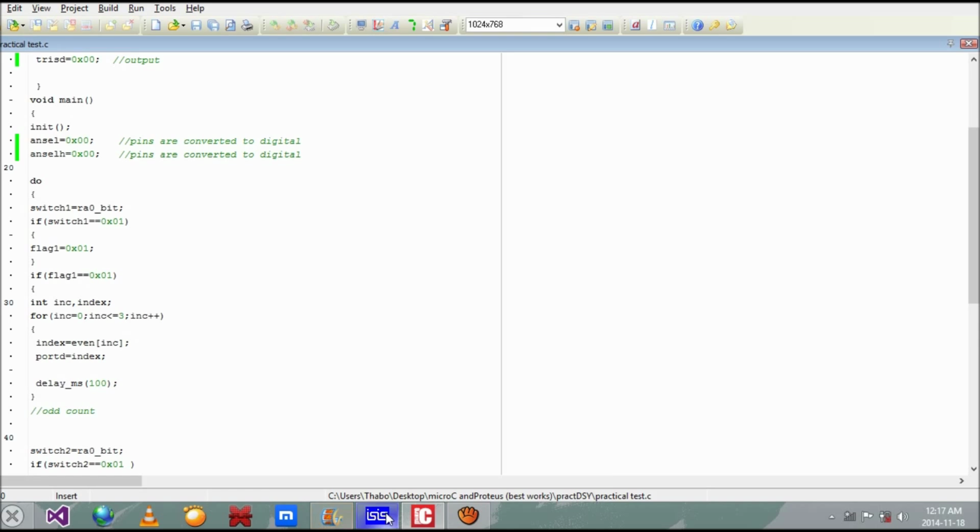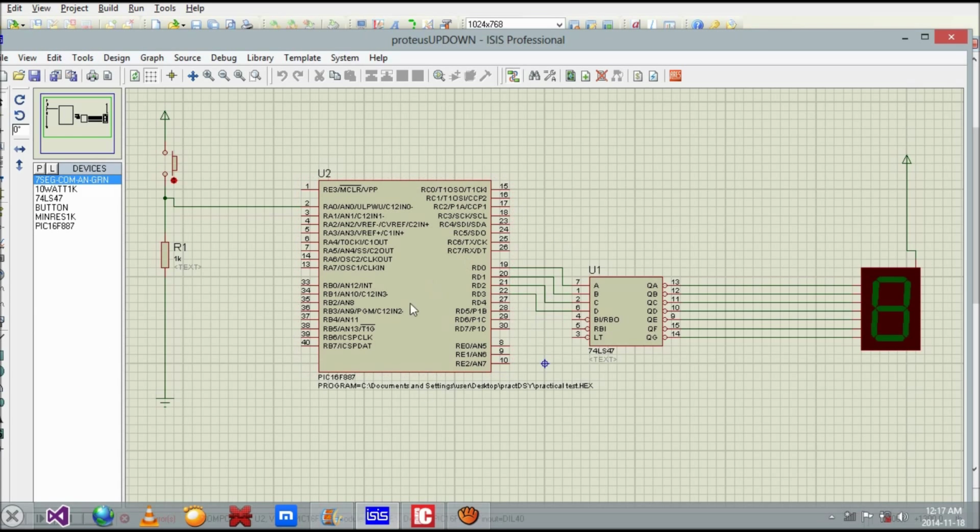And port D on this sketch is connected to a decoder, which is connected to a 7 segment display of a common anode, right? And then all those values will be brought here, but they'll be decoded first to binary, because it's BCD 0 to 9, these numbers will come to A, B, C, D, and then they'll be decoded here to binary, right?